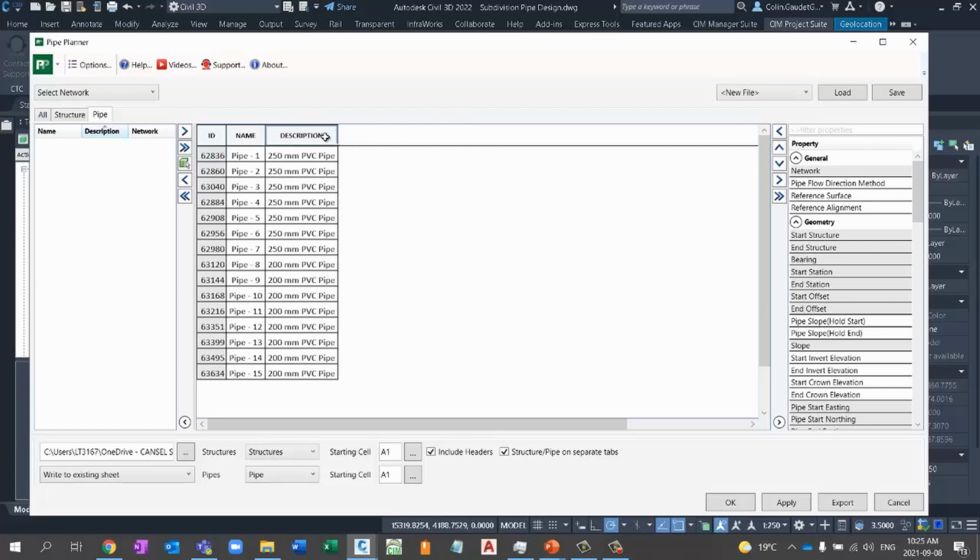So remember I said right click is your friend. I'm able to insert a column to the right. Now it shows up as C1, but I can absolutely rename that. And maybe this is my VFlow Max. Well, VFlow Max isn't something that you pull out of the part properties. This is a formula based on the different pipe properties and the location and things like that.